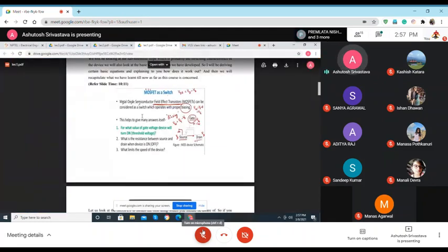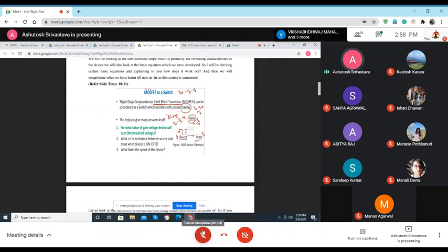So basically, by applying this external bias, you have what you call the inversion layer that forms, not the depletion layer. Through this inversion layer, there is the movement of the charge carriers.